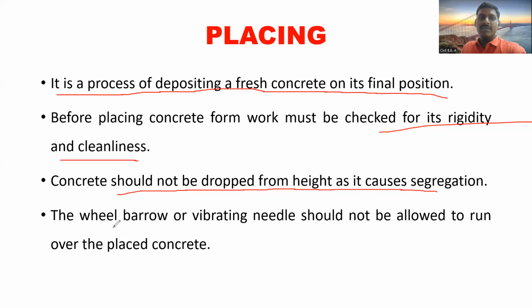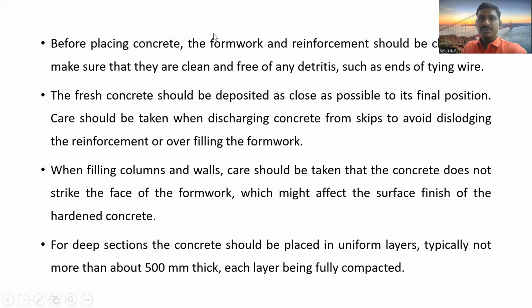Then the wheelbarrow or vibrating needle should not be allowed to run over the placed concrete. So this is related to placing of concrete. Again, you can see what we have to know about placing of concrete.